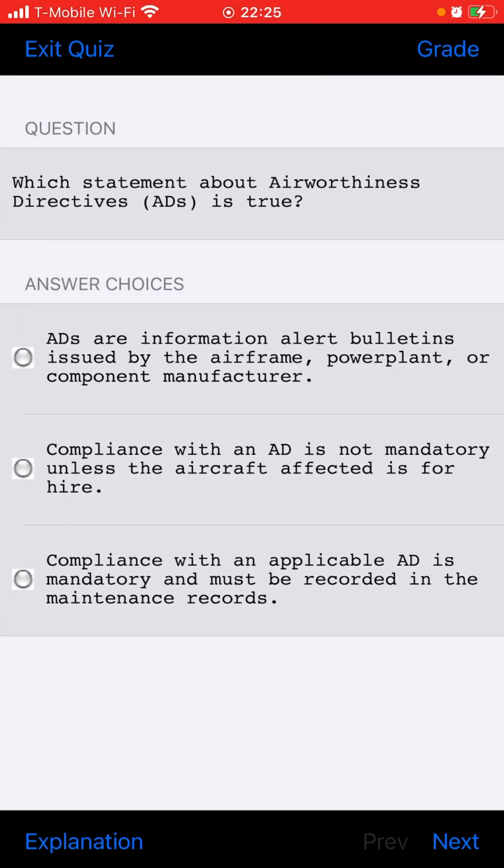What are three basic autopilot commands? Sensing element, gyros, output element, servos, command element, flight controller, computing element, computer and amplifier. What are the sensing elements of an autopilot system? The directional gyro, turn and bank gyro, attitude gyro, and altitude control.